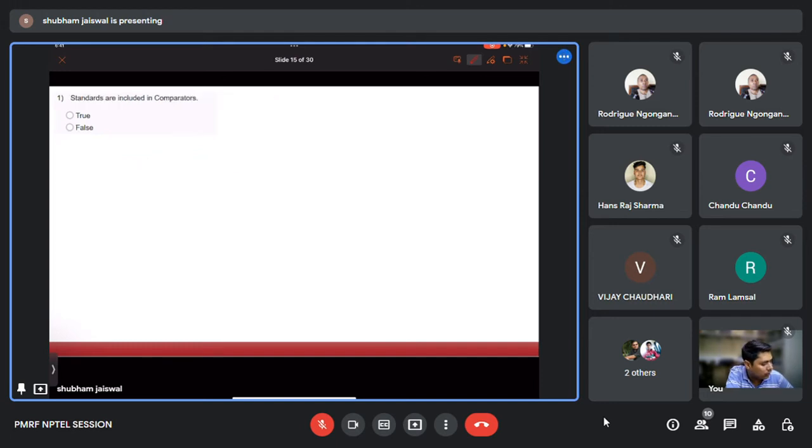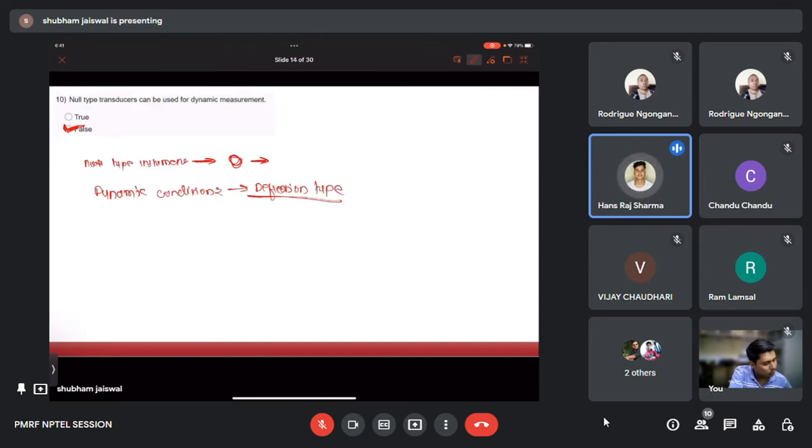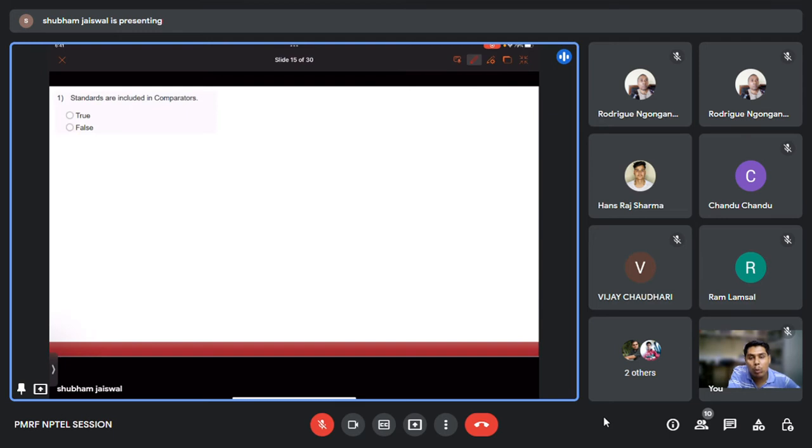So moving to our next question. Sorry, sir, about the last question: null type transducers are more accurate, right, sir? They are more accurate when it comes to static measurement, meaning there is no fluctuation at all. But when there are fluctuations, suppose this is my pointer and this is my zero position. In null type, it will have some offset, and we try to bring it back to our zero position.